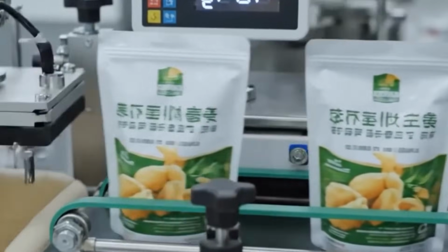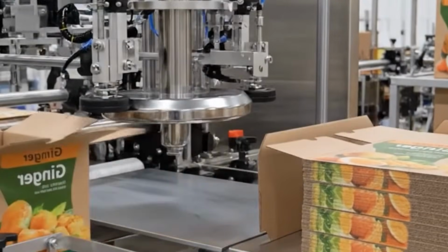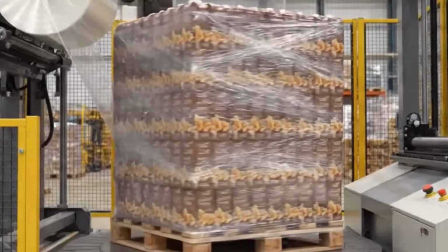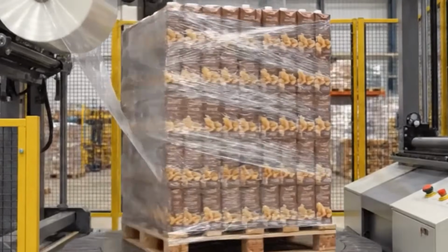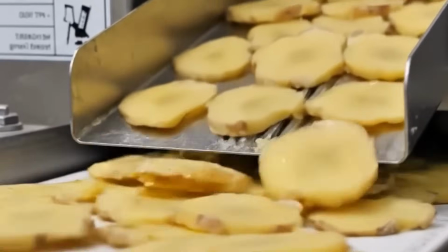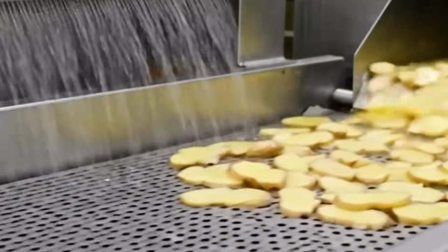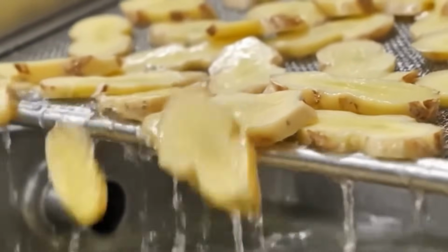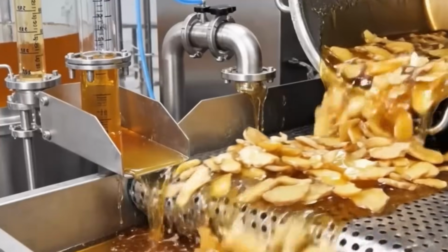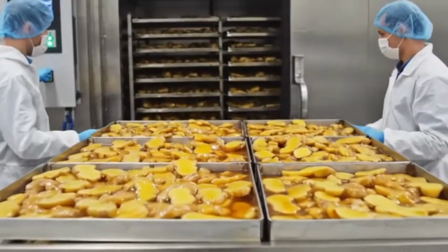After homogenization, it is flash pasteurized by pumping through a plate heat exchanger system, reaching temperatures above 85 degrees Celsius for a few seconds, and then rapidly cooled using a countercurrent chilling loop. The syrup is passed through sterile filters and transferred into insulated holding tanks with nitrogen blankets to prevent oxidation and maintain flavor integrity. With syrup and water prepared, they are combined using an inline blending system.